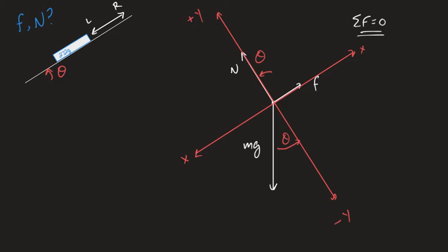Now, this object didn't move, but if it were to slide, wouldn't it slide this way? You will be happier in your future if you put the positive direction in the direction of likely motion. I promise, especially the problem I'm going to give you tonight. Now, I'm not saying change what you did. I'm just saying in your notes, give yourself that direction. You'll always be happier if you make your positive direction the direction of motion, or the likely direction of motion.